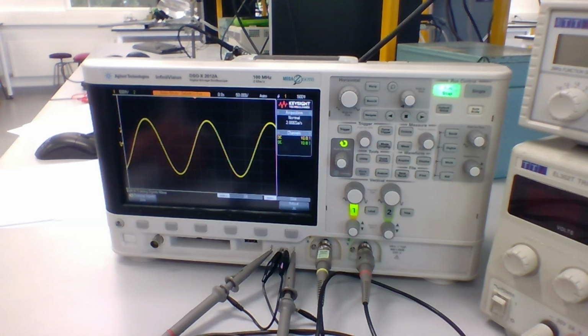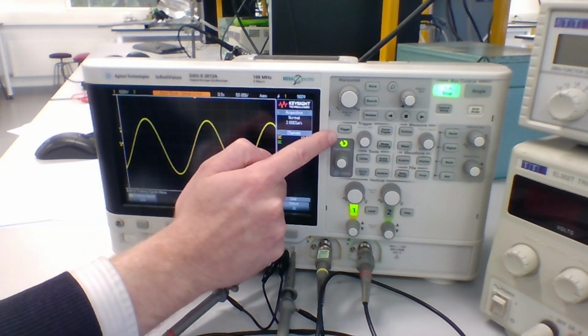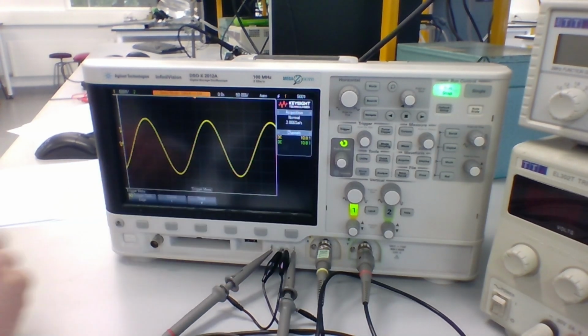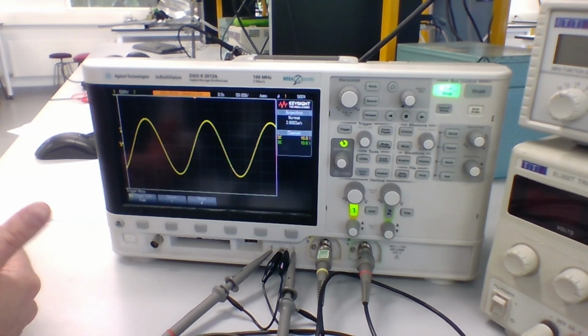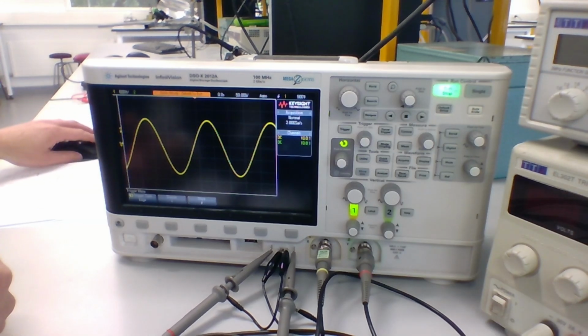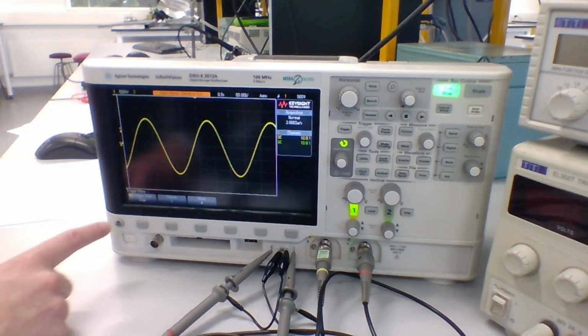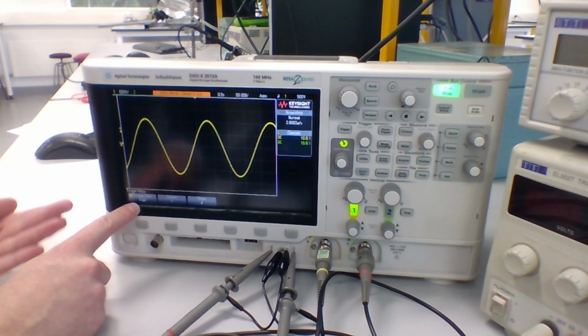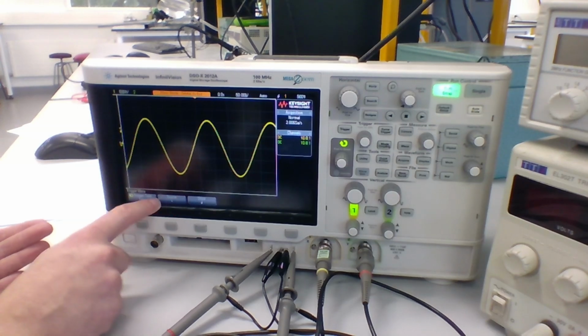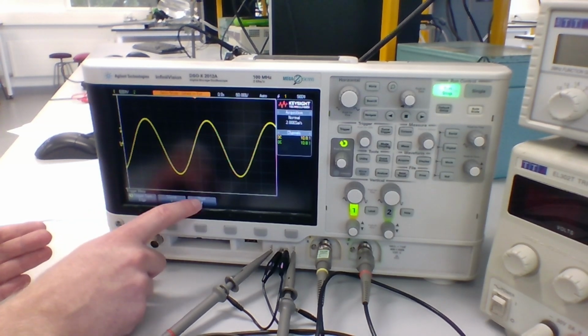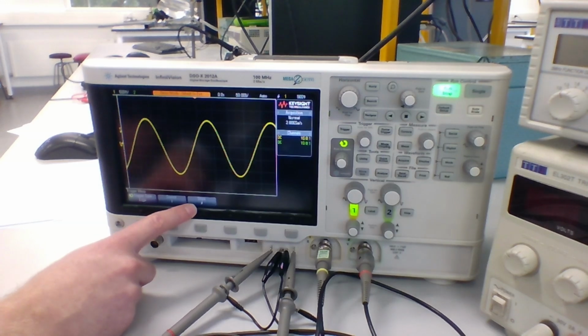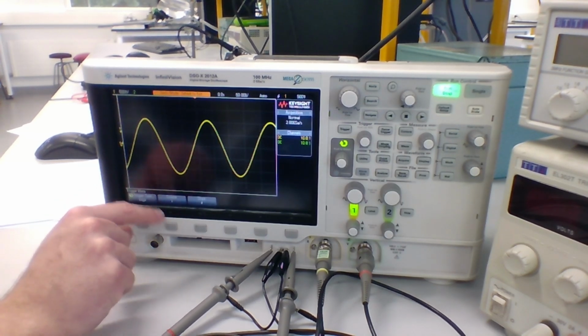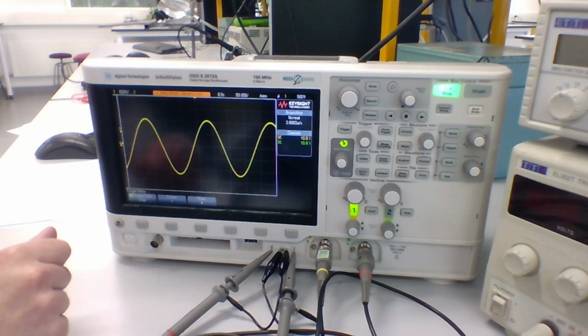And then what we're going to do is look at the trigger menu. So you'll see there's a button here labeled trigger. We press that. That takes us to the trigger menu. And this is where we can change or look at the settings of how we are triggering the oscilloscope. At the moment, we are triggering on edges. So we're looking at our edge on the signal. It's triggering off of channel 1. And it's looking at a rising edge, which is what this little symbol here is showing. It's showing something going up with an arrow pointing up.